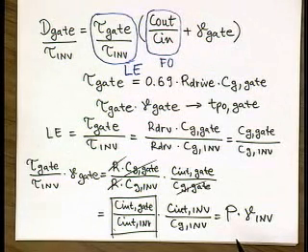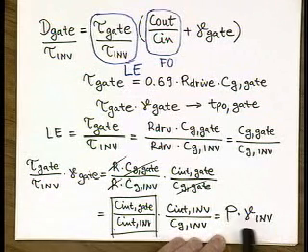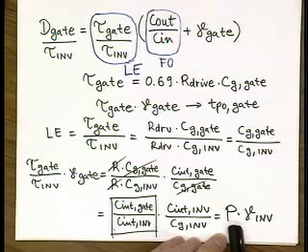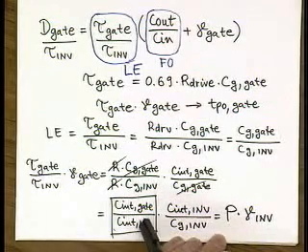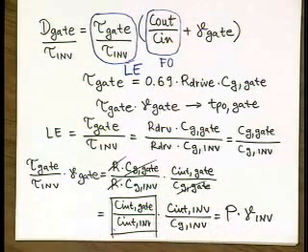That is basically a delay of this self-loaded gate without any external load. So it's basically TP0 for a gate. What this basically tells you is that TP0 of a gate is P times larger than the TP0 of an inverter. And this makes sense because they have the same pull up and pull down resistance, only their capacitance ratio is P times larger. So you have P times more capacitance at the output than in the case of an inverter, and therefore you have P times larger delay because the resistance is the same. And that's all you need to remember basically to get started with this logical effort analysis.